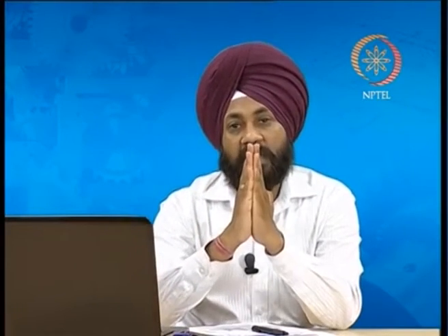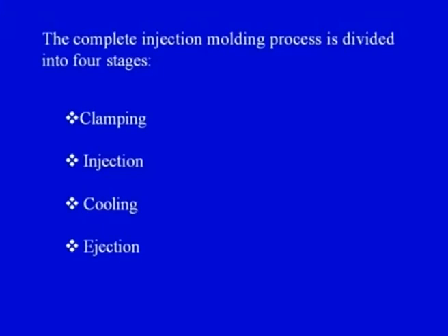Because the cavity is generated or cut inside the two mold halves. So one mold half is fixed, another mold half is movable. The movable half would travel towards the fixed half and the two mold halves would be clamped together, forming a cavity inside. So the first stage is the clamping or the formation of the mold cavity. So first stage is clamping.